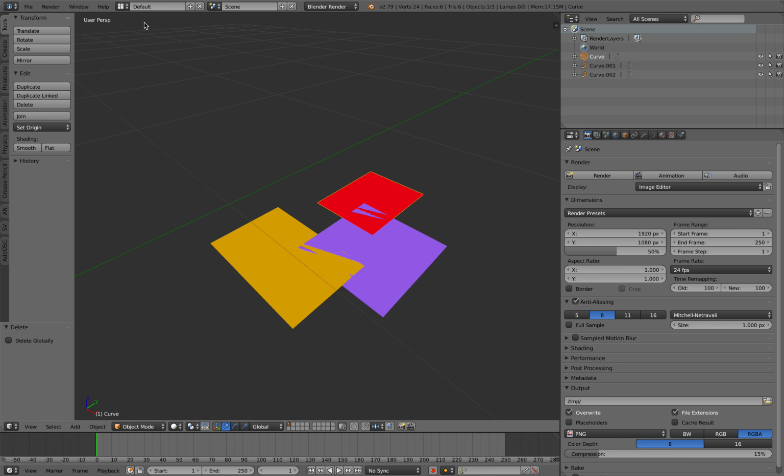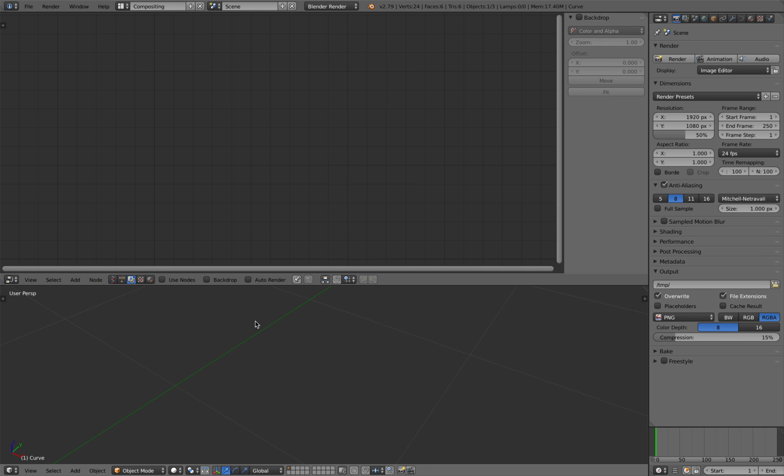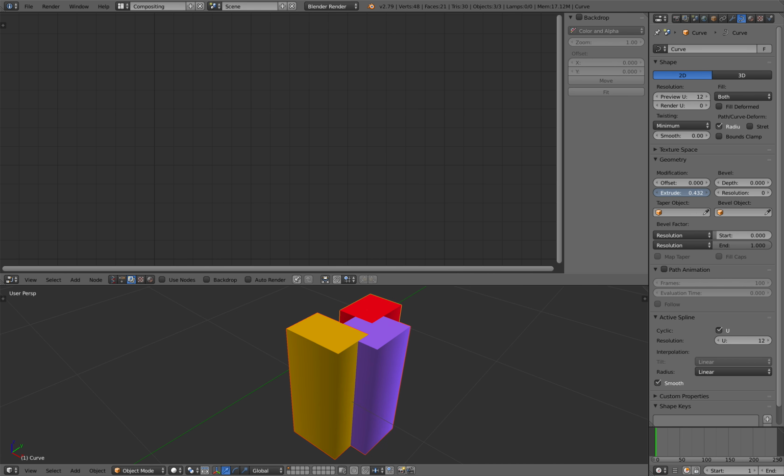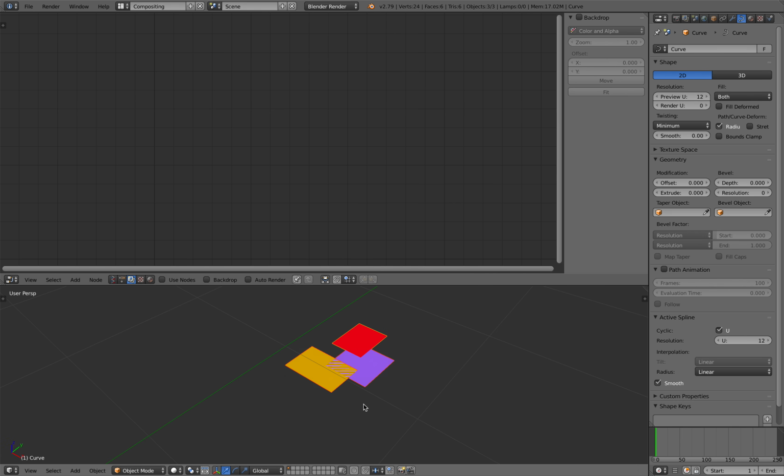If you don't want them to be overlapping, you can use Sverchok nodes for that. I'm gonna be using Sverchok. By the way, these guys are curves. So if you select the curve and then extrude, it's easily going to become a 3D object. If you want to extrude them all at the same time, you can select them in Blender, shift select, then hold option on Mac, and drag to extrude. That's a nice little trick there. They are still overlapping though, so we're gonna fix that first.